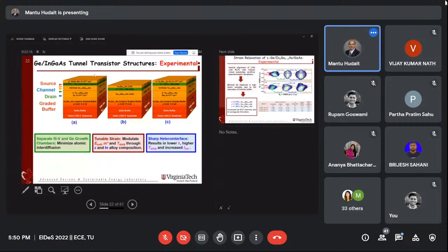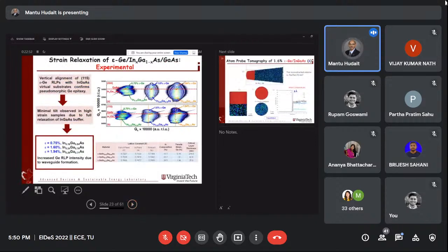So you can see how to confine the carrier, and the top part, that interface, is the most challenging interface. That means once you grow this material, cross doping has to be prevented, interdiffusion has to be prevented, defects have to be prevented, and a smooth interface and lattice matching must be there if you grow on silicon. So these are the different strains, as you can see here, and these are the sharp interfaces. We need that, and we characterize those materials using our X-ray.